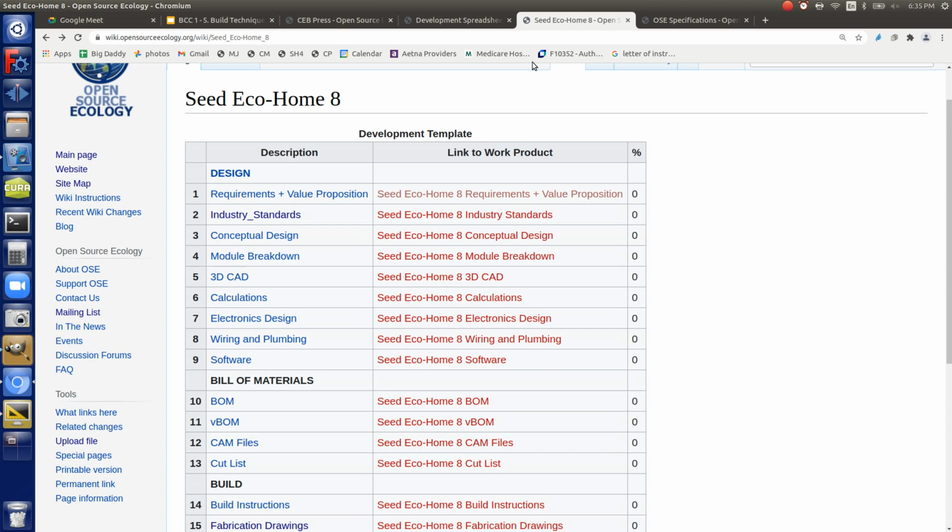If you have a concept, okay, I think it works such and such. Start breaking it down so that if you have a team, many people can develop it at the same time. If you define modules, you have to define interfaces, how they fit together. You can't just tell people, do the loader arms, you do the wheels, you do the frame. You have to tell them how the loader arms attach, how the wheels attach. For each one, you have to define interfaces. It's called interface design. We don't have that explicitly here, but it's under module breakdown.